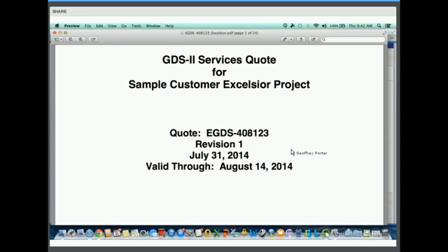Great. Okay. Then a related question: is mask yield taken into account for gross die per wafer? I'm not sure what mask yield means in this context, but gross die per wafer is calculated based on the die size, the aspect ratio of that die, and the wafer diameter. The user who asked the question probably knows there are many ways to calculate gross die per wafer, and we have a lot of experience in trading those different formulas off and coming up with what we believe is going to be within 1.5 to 2%, if not a smaller range, of what the actual gross die per wafer will end up being.